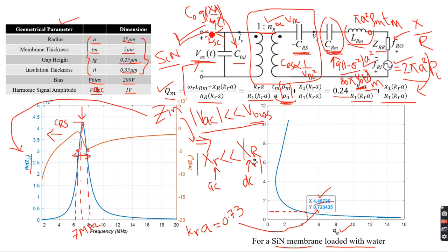And for this linear circuit model, you can derive the mechanical quality factor in terms of its lumped components. That's again omega L over R, as you know from your basic circuit theory class. You can plot this as a function of resonance K versus QM, and then you can also find the limits of what you can have.